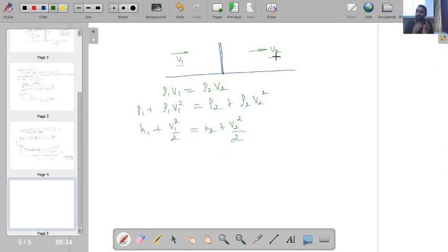But if I change the situation slightly and consider the case of an aeroplane, actually my flow is stationary, but the shock wave is moving with the aeroplane. Now if I place the observer in the frame of the aeroplane, then with reference to that observer sitting on the aeroplane, he will find that the shock wave is stationary but the fluid is moving.